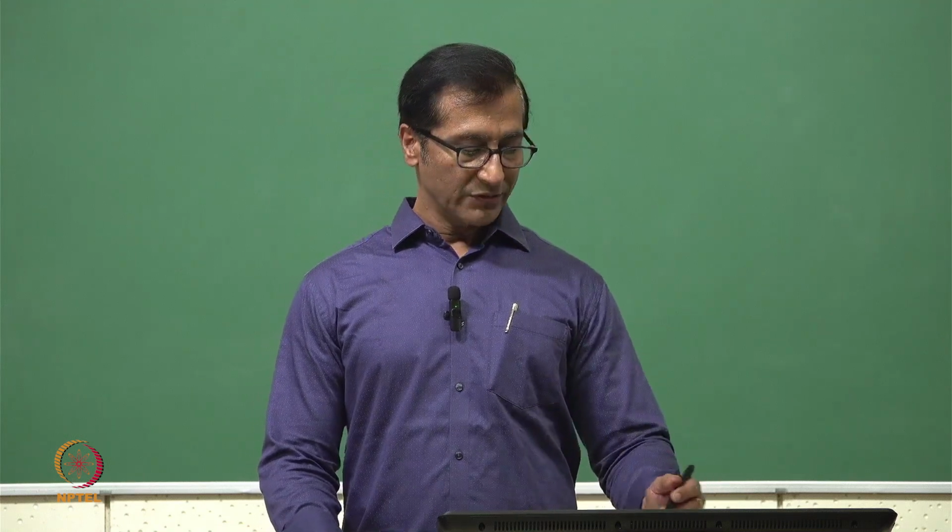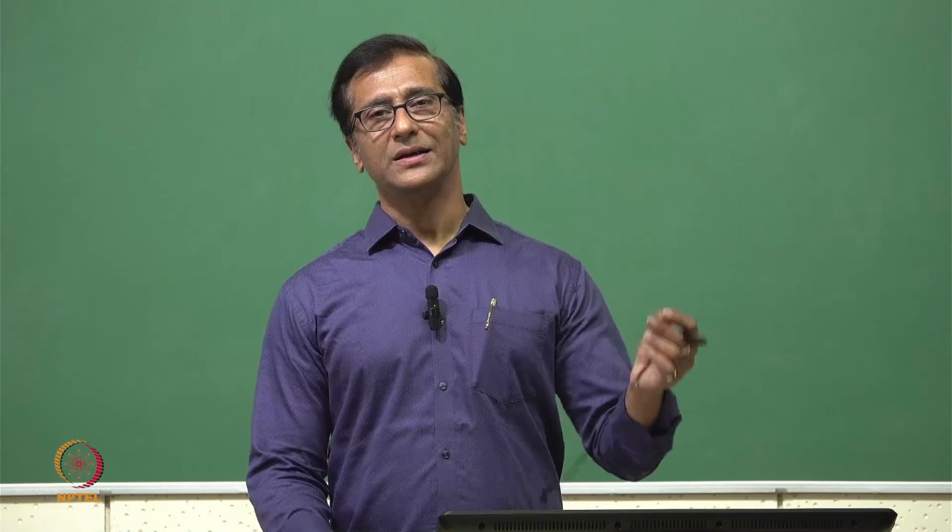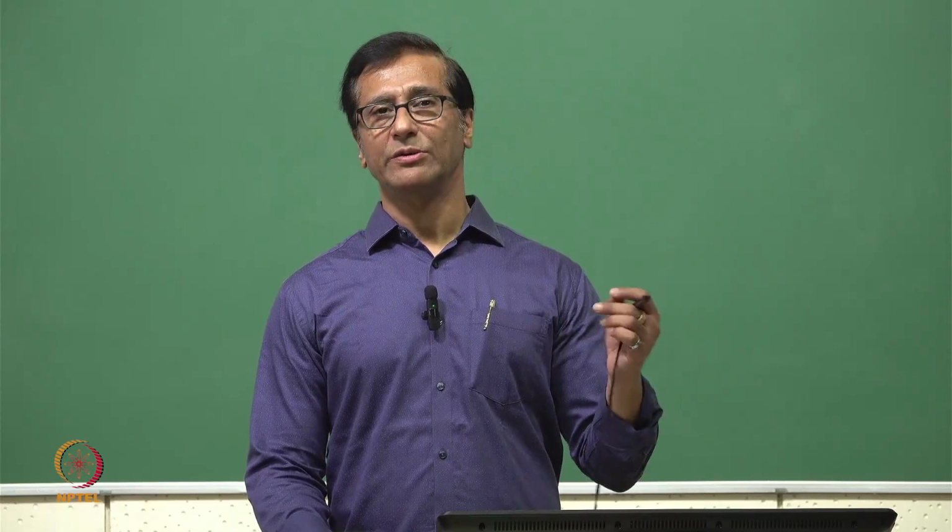It's kind of some guidance that we prefer to go ahead with the EHL. As I mentioned, the wear rate in EHL and full film lubrication will vary to some extent, but not significantly. The only drawback of the EHL is that it is a really narrow region, and if temperature or pressure goes beyond the limit, or misalignment comes, then it will move to the mixed lubrication, boundary lubrication.